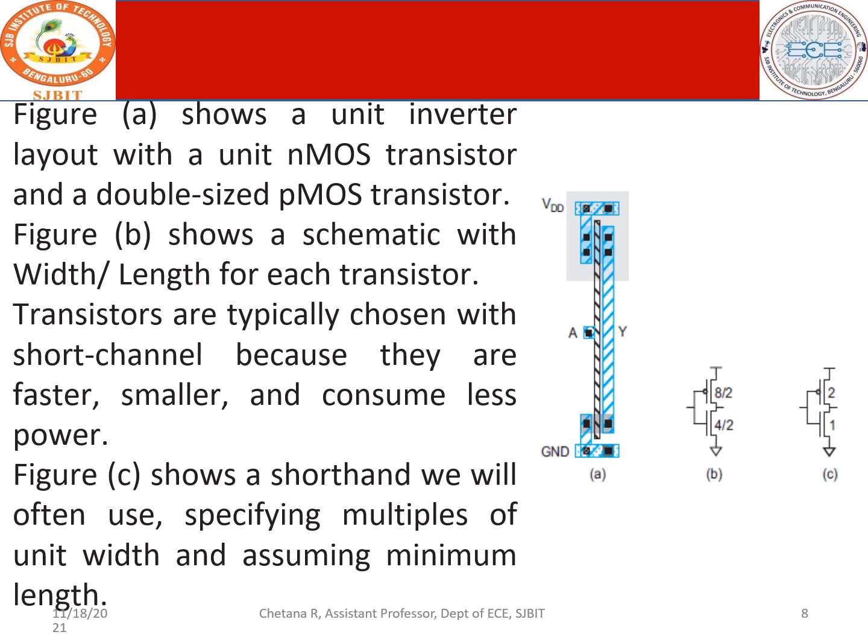So this is how we need to construct, keeping this in mind. In order to get 2, it is nothing but W by L, so your W should be 2 and L should be 1. The minimum width of the diffusion is 4 lambda, so less than 4 you can't use.